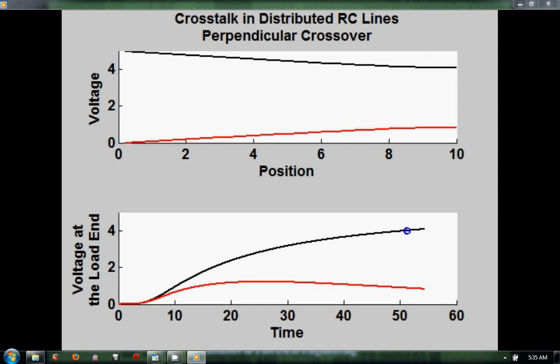The crosstalk that was demonstrated in MATLAB can be dangerous in ICs. For lines being driven, crosstalk increases their delay, and for stationary lines, crosstalk can introduce transient errors. In dynamic logic, this could cause the state of a node to flip, causing a permanent error. To ensure performance and reliability of an IC design, this detrimental phenomenon must be minimized.